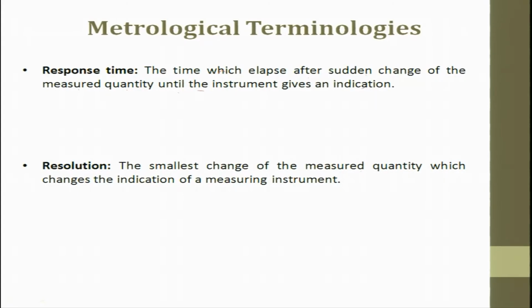What is resolution? The smallest change of the measured quantity which changes the indication of the measuring equipment or instrument is nothing but resolution. For example, if you have data 10, 11, 12, 13, 14, the resolution is 1. Let us assume these are all values.